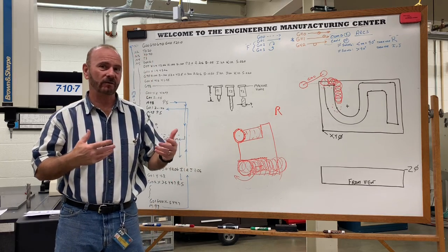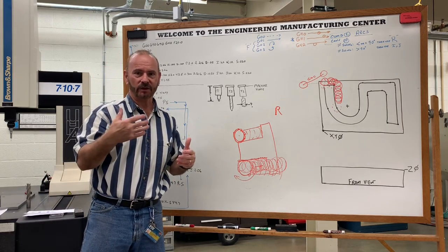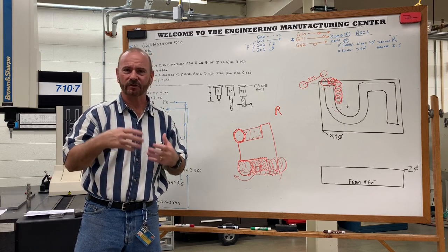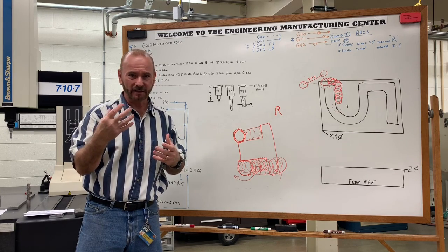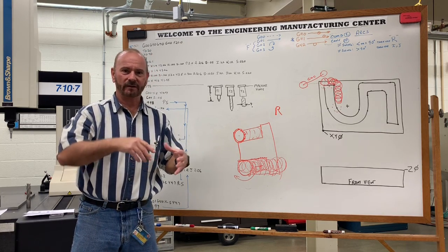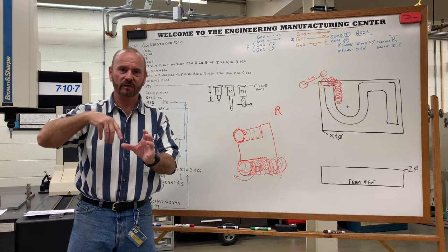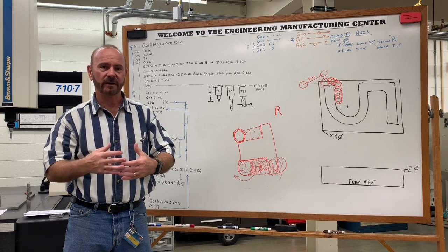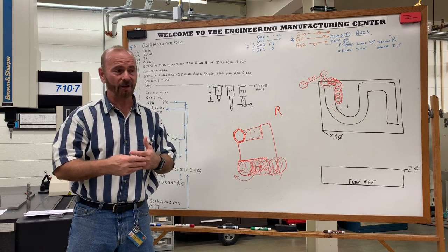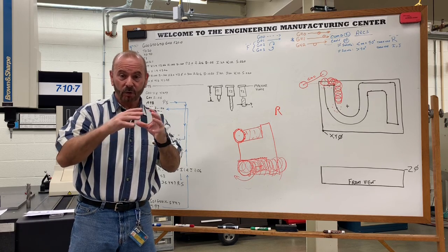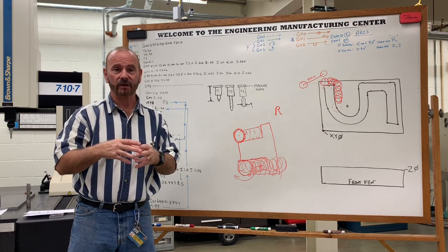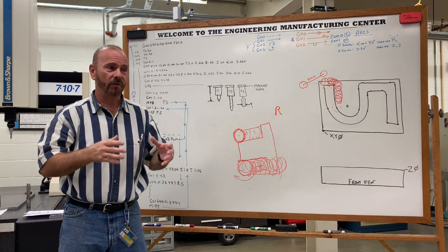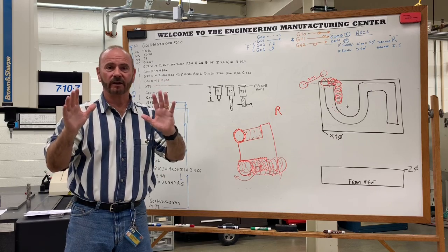And one of the ways that we do that on machines is the cutters will generally talk back to us. When that cutter that you engage into the material starts squeaking, and it's kind of yelling back at you, that tells you that the cutter is spinning faster than it's removing the material. And you have to do one of two things: either slow down the RPM or increase the feed rate. If the cutter's growling at you really, really loud, well, that means that now you're pushing the cutter harder than it can go, and you need to either increase the RPM or decrease the feed rate. So those are signs that we use when we are cutting in certain materials.